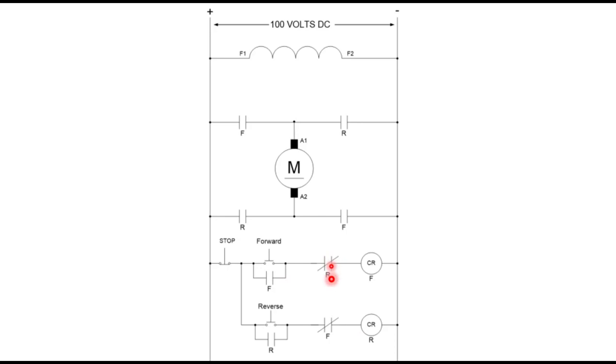And these are my electrical interlocks, like what we talked about last week. We were talking about the garage door opener. This is another example. It's not just a matter of trying to get the motor to go two different directions at one time, because it won't. Here's what will happen.